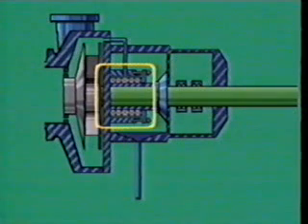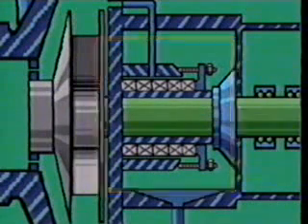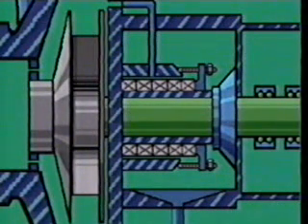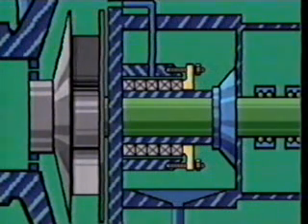Now let's take a look at the stuffing box. It holds the packing gland. That gland, in turn, is designed to regulate fluid leakage around the shaft. We'll talk more about pump packing in the next section. A gland follower is also found with the stuffing box. Basically, it's a bushing designed to hold and compress the packing gland in the stuffing box. Bolts usually hold gland followers in place. They're also used to adjust the gland follower's position.